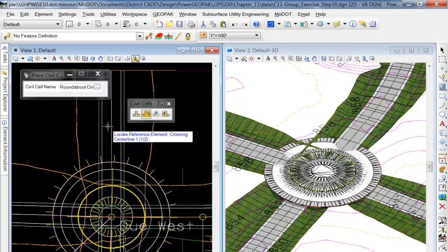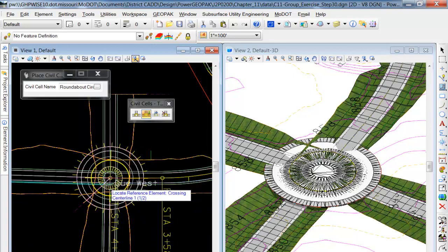So it only goes by what it knows. If you're telling it that these roads are using the existing center line, and this is flat and placed on there and maybe has a little bit of slope off of it, it's not going to match exactly on these two sides because you didn't pick those two lines on that side. So it could be warped a little bit. Where this leg comes in may not match exactly over here, but if you create a new profile along those corridors and raise it up a little bit or down, whatever it needs, then it'll match up perfectly. So you can see this portion of the class could be a whole day if we wanted it to be, just putting all this stuff in.